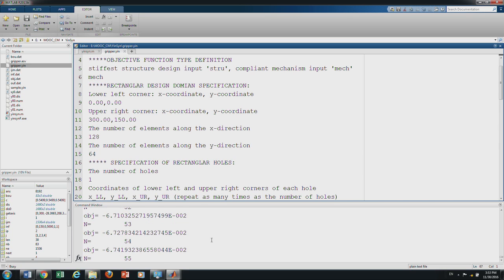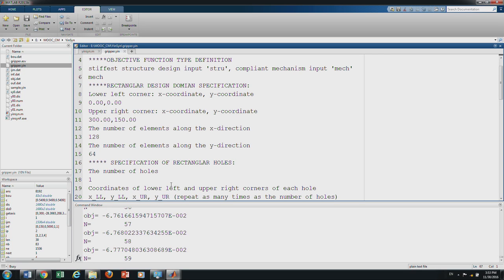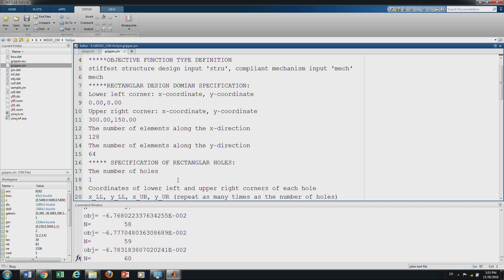So, that is how the time is going, not in the updating and the inner loop to determine lambda and gamma. All of that is happening when it goes from, let us say, 56 to 57: two finite element analyses and the update to satisfy the volume constraint, which is just linear. In fact, here we do not have lambda and gamma, we only have lambda corresponding to the volume constraint.